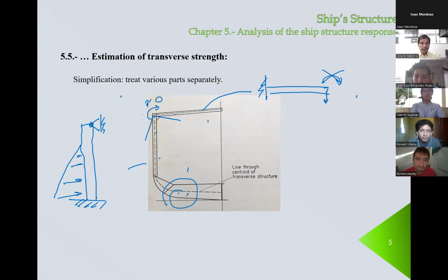Because if you try to move in this direction, it's very difficult that you compress this element too much, so that it moves a quantifiable amount. But the rotation is a problem. So what we can do is include a corresponding torsional spring. So in this case, we could consider one single beam, clamped at the bottom, simply supported with a torsional spring on the upper right, and then loading, which varies linearly because of the hydrostatic pressure.